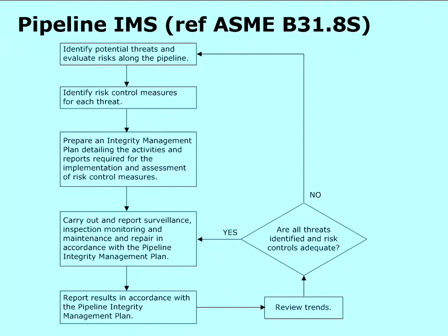So what if you're trying to control a particular defect, and you notice that you've controlled the defect, but when you check, like a surveillance, you notice another issue? So you keep doing this for the control one and start another one. Absolutely, yes. So you've got to have something like this for all of your damage mechanisms. You've got to have all of your damage mechanisms picked up at the very first stage where you're identifying the potential threats. And that's why the publication of standard damage mechanisms is so important, because you need to start off with a checklist, and that checklist has got to reflect what other people have found.